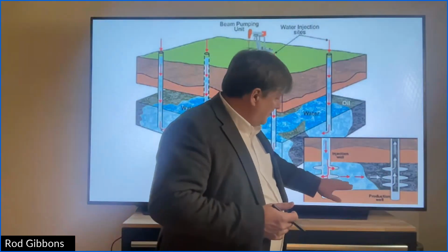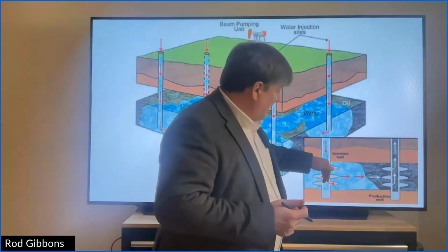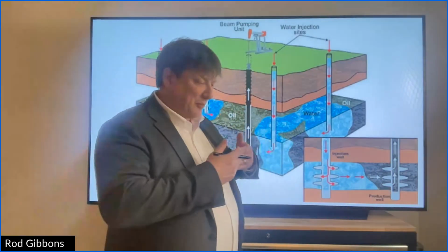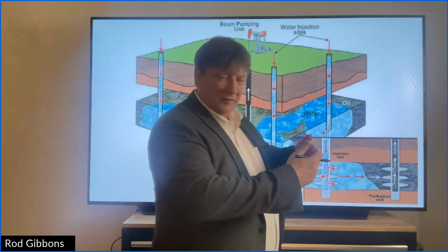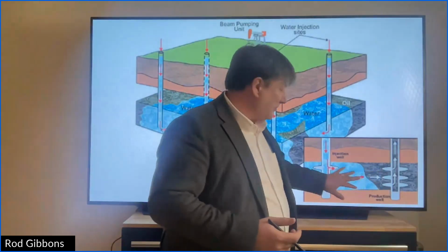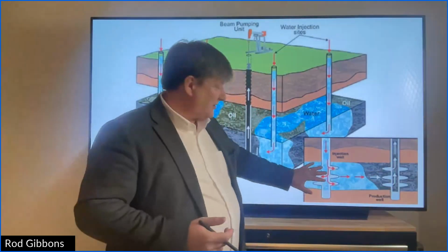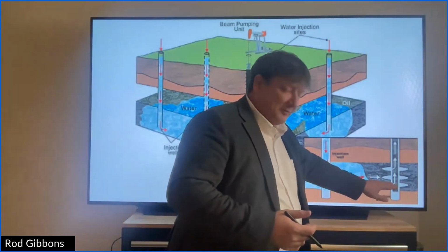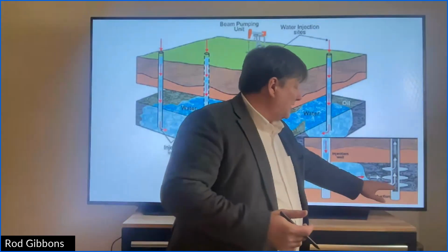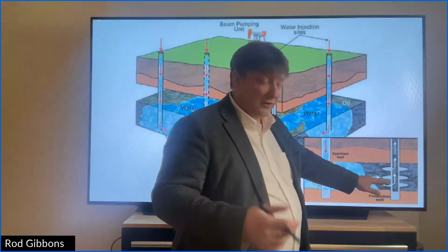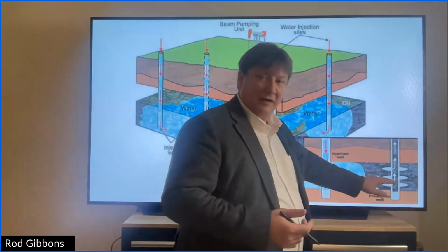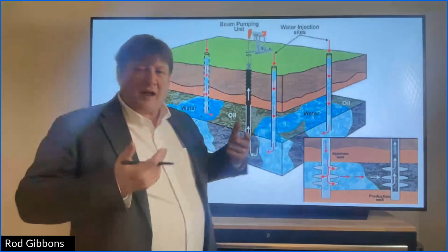Sometimes, most times, this is not a perfect flood front, not the perfect straight water flood. You'll get some fingering going through because the rock quality is different in this section. So you could get this bottom section water out first. Then you go from 100% oil cut to maybe 80%, and as the water goes along here, your water cut will get higher and higher.